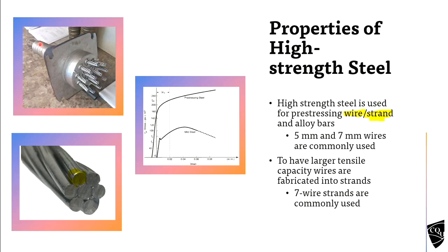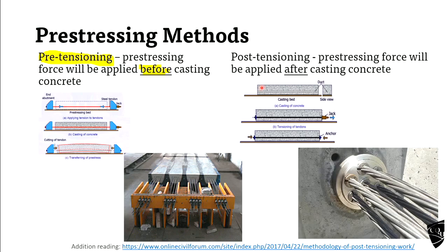You see this is the duct. Okay, so you can think of a pipe. So we put a pipe here, or duct here. During the construction we put a pipe there and put the concrete and cast it. Once it hardened, after 7 days or something, we insert a steel wire. Okay, we insert a steel wire and fix this side.